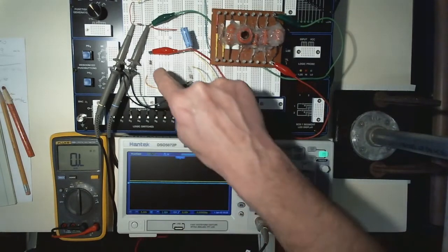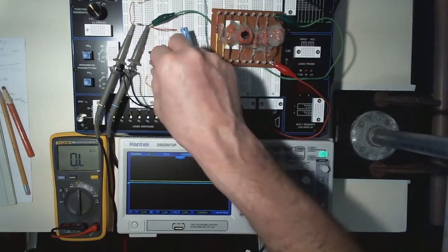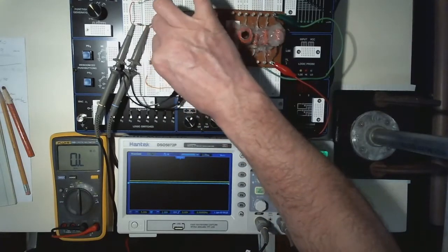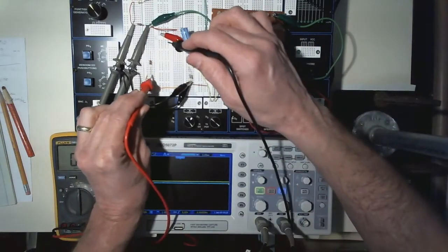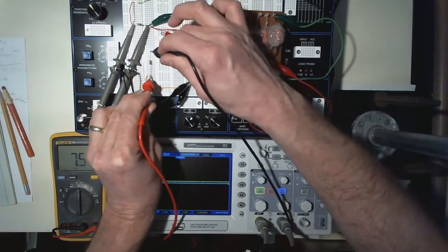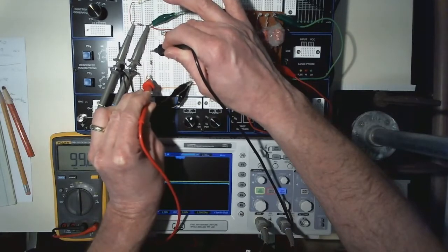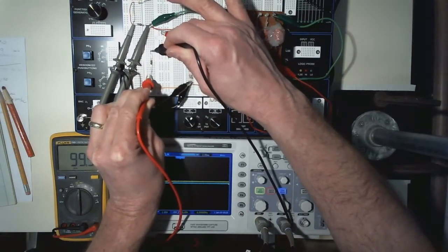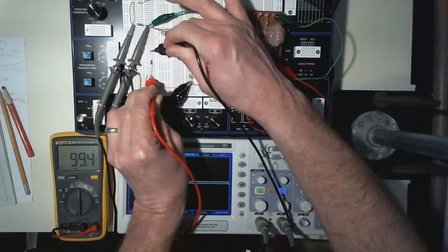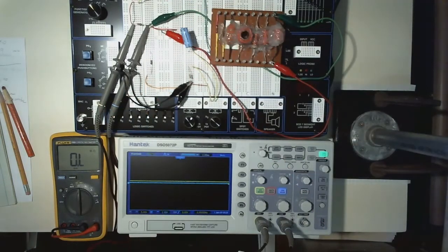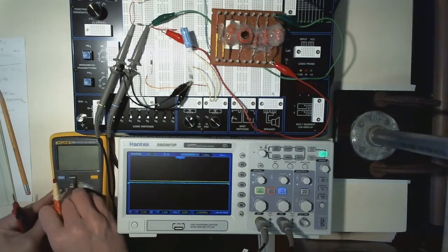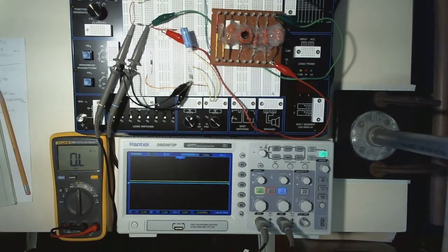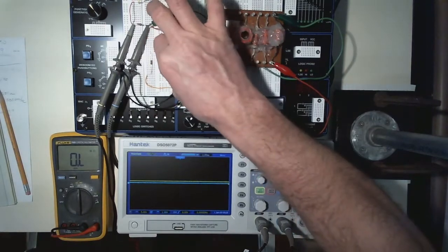Then I want to come down here to these resistors. This resistor is R2. So I think if I just unhook that, I can get it isolated. Remember, this should be about 100. And it is 99.5. Got my hands in the way there, sorry. 99.4. Not sure what's beeping at me. I think this is so 99.4 ohms. I'll hook that back up.